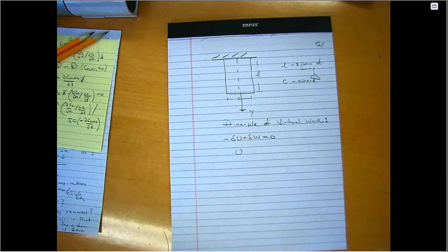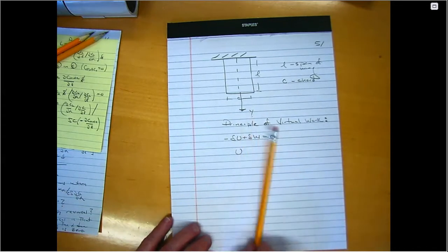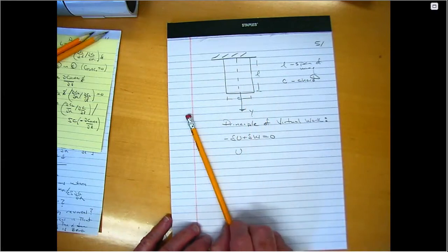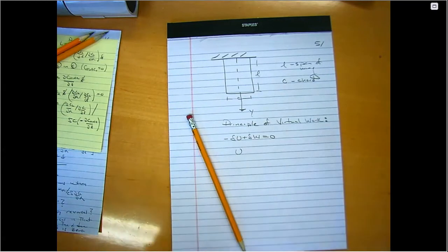But if I want to do an analysis for something that looks more like even a wind tunnel model, even a simple low-speed wind tunnel model, let alone an advanced design, I need a more elaborate means of describing the behavior. And the next step up, not the final step, but the next step up, is to look at something that looks like a wing with a large span and a small chord, and therefore can be treated as something that still twists, but it twists in various ways along the span.